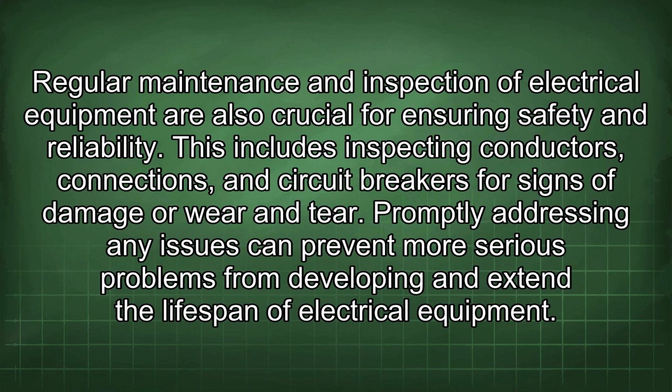This includes inspecting conductors, connections, and circuit breakers for signs of damage or wear and tear. Promptly addressing any issues can prevent more serious problems from developing and extend the lifespan of electrical equipment.